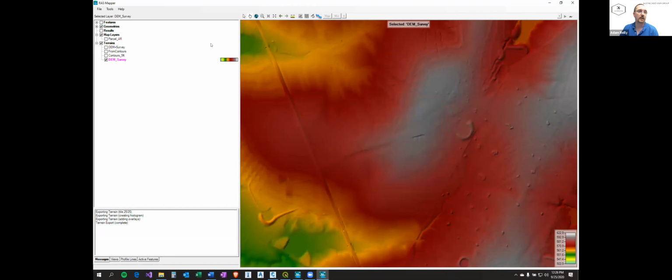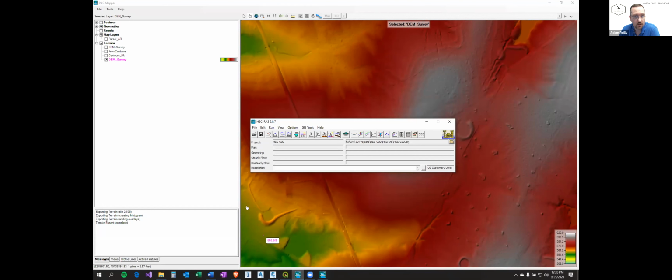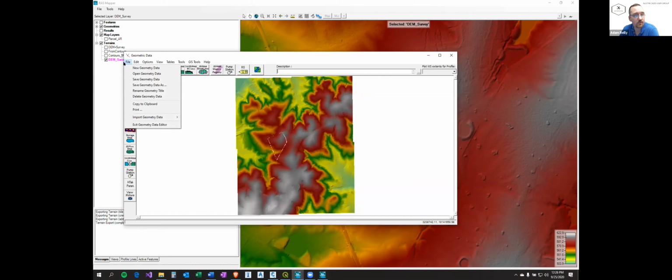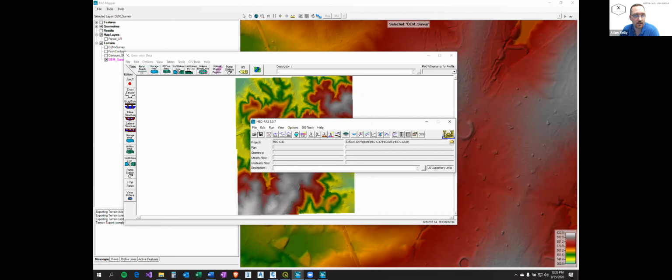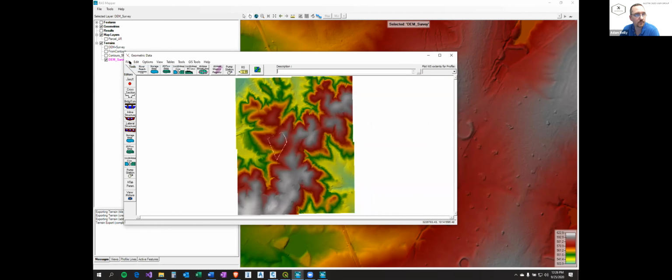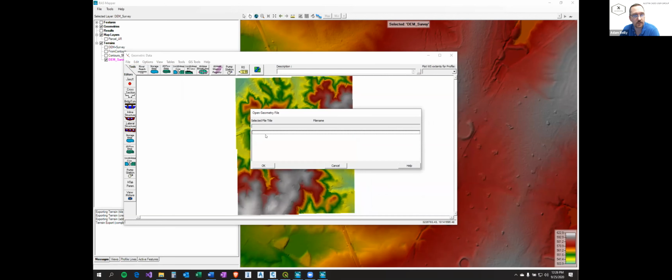And if you've already got a geometry file created, you can add them directly to that. If you don't already have a geometry file, in the main dialog for HEC-RAS, click the little View Edit Geometric Data button, come over to File and click New Geometry Data, and give it a title and file name. So I already have one created, so I'm just going to keep this one. Let me open that so it's just attached to this.